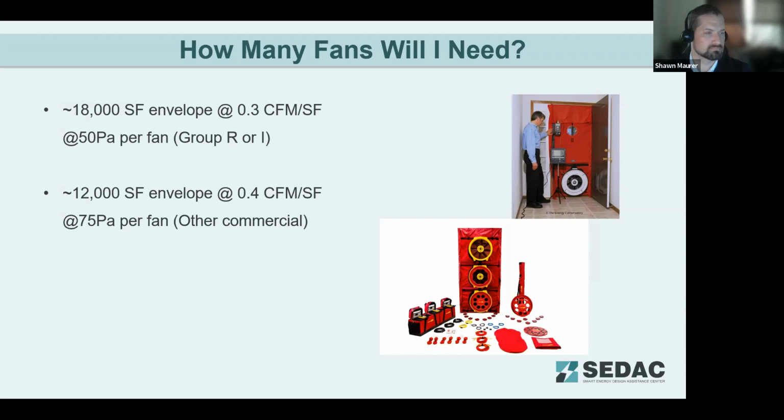Fortunately, with warehouses, your leakage points are going to be probably fairly obvious because a lot of warehouses are tilt-up precast concrete, with sealed joints between it. So your leakage points are probably not going to be in the walls themselves, but they're probably going to be at your loading dock doors. And did you specify loading dock doors with good air sealing, roof to wall intersections? That's going to be a real leakage point for warehouses. So again, this is going to be for new construction that this is going to be required. So existing renovations and alterations will not require blower door testing.